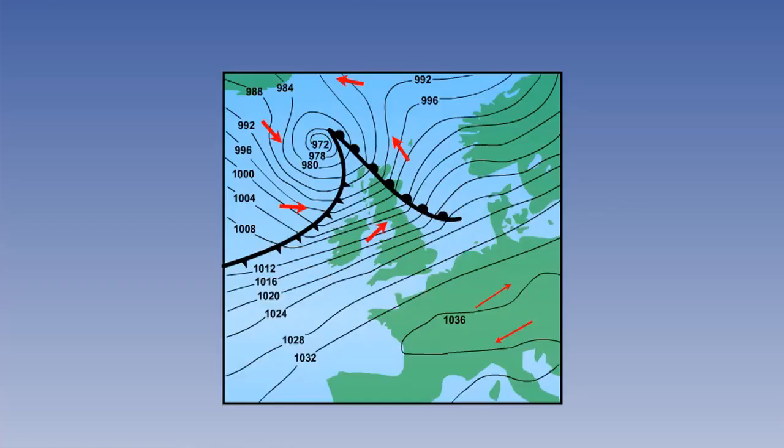There can be several causes of low-level wind shear. The first we shall look at is the passage of a front, in which the isobars change direction and thus often become more widely or more closely spaced, giving not only a change in direction, but also a change in speed. Generally speaking, these changes are fairly gradual, but a deep depression with strong winds can produce significant wind shear.